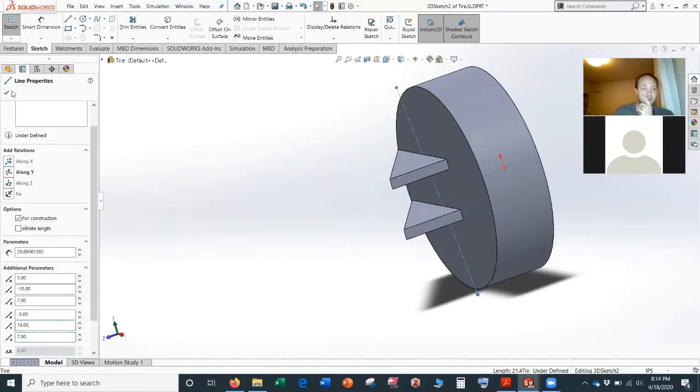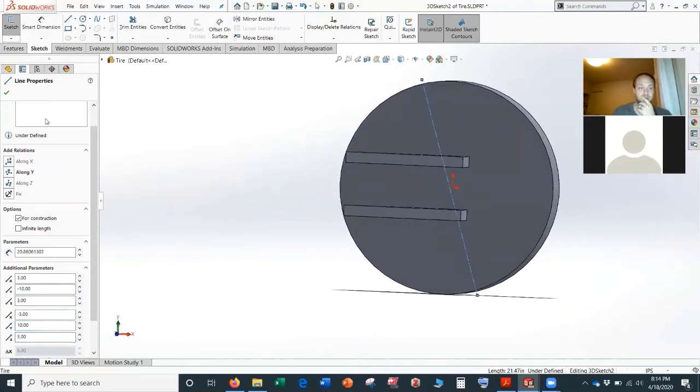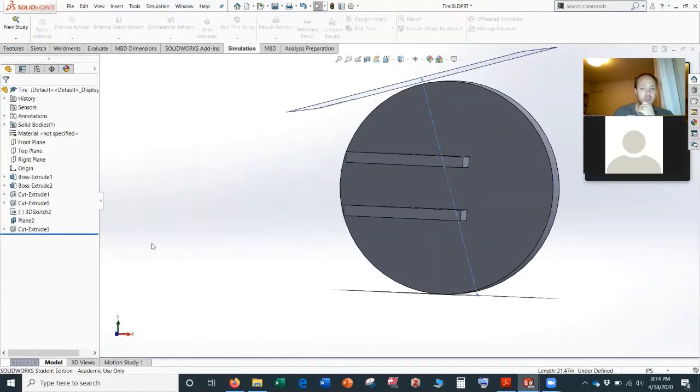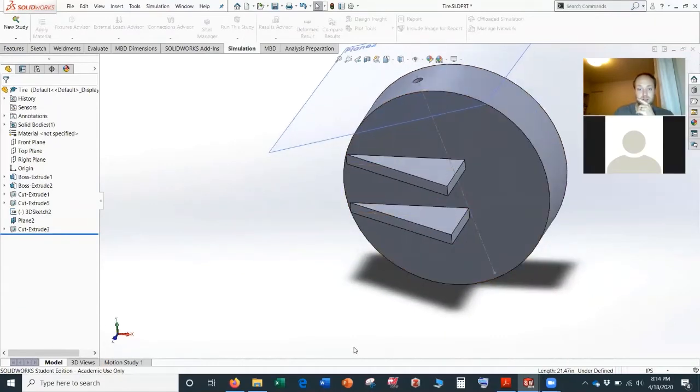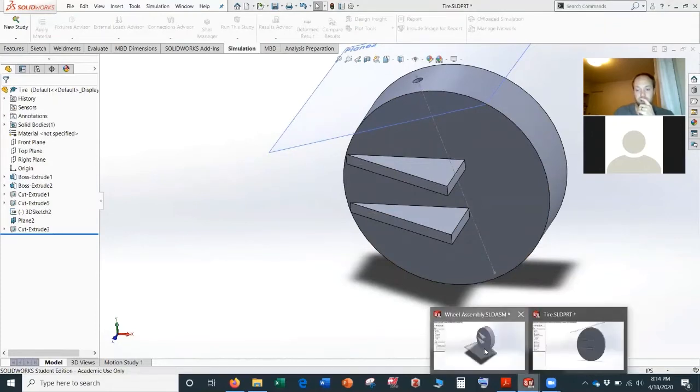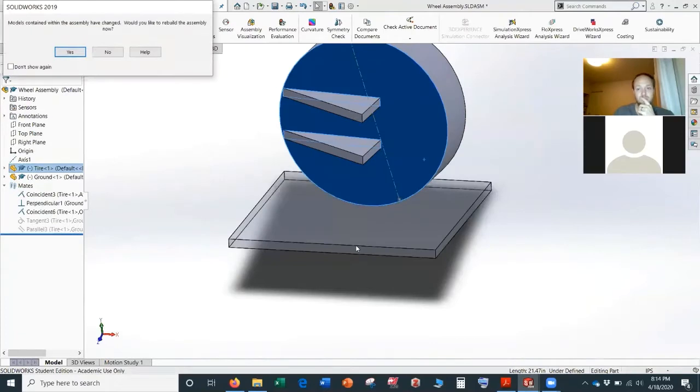All right, so we have a little bit of scrub radius, but no kingpin inclination. If we have a little bit of time, let's just do caster. We'll do no effects in that direction. Okay, so obviously our kingpin inclination is 0. Our scrub radius is 0, but we have some trail and some caster. So we'll just look at those together, since they're pretty much always going to go together.